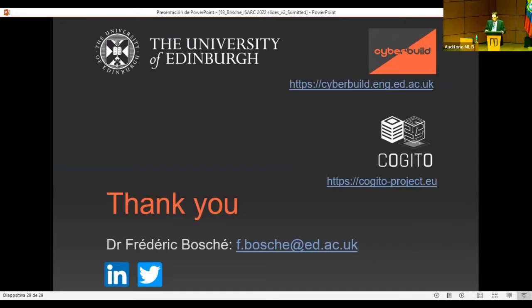So I didn't have it as part of my presentation, but this information is actually stored in the digital twin platform. We developed a data model and are developing an ontology for storing geometric quality control data, so that it can easily be queried. Through our interfaces, somebody may want to query, show me all the column verticality results for that project. That can be easily queried through the graph network that represents the digital twin platform, or show me the quality control for all the columns or a specific component, etc.